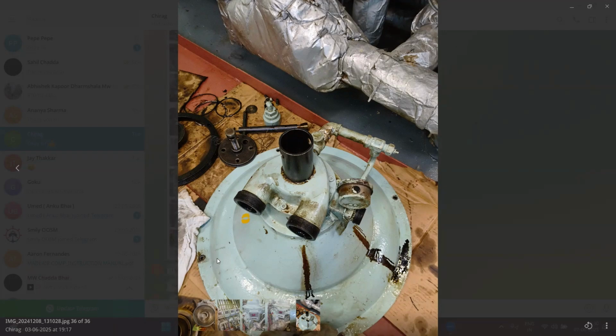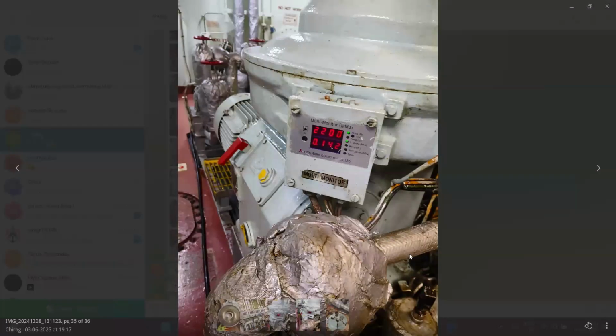Which valve, sir? There is a valve here, right? Can you see this line? This line is, and the valve is I think broken or something. Okay, this is a non-return valve and this is a normal valve. So this is open to make it a clarifier. So nothing you have to do in this type of purifier. Okay, so there is a back pressure valve. It is not visible at this moment.